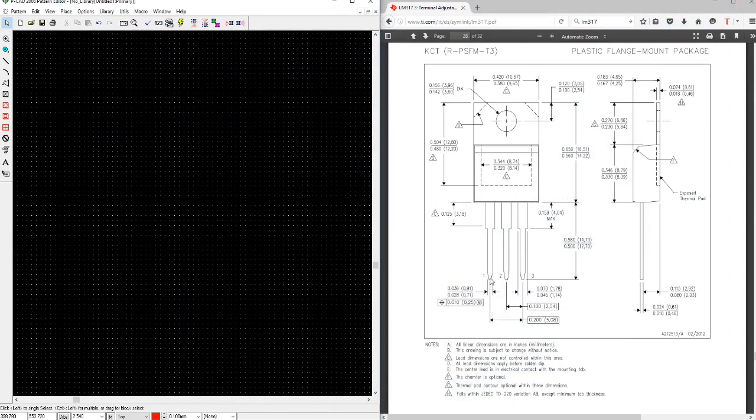Second thing we need to know is the pitch between these components. Now, typical through-hole components come from the 1960s and 1970s, where components were originally created on a 100 mil pitch, or a 2.54 millimeter pitch. Modern components are not created in mils anymore, except in the States, where they are still stuck on working in inches. The rest of the world is working in millimeters, so you will find that through-hole components tend to go to inches, hence mils, and surface mount components will primarily go on the millimeter unit scale. So based on that, we are expecting to see mils here.